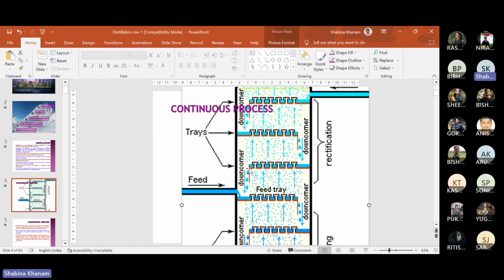Okay, so between here to here, we can say holes are available. That is from inlet downcomer to outlet weir, right? Inlet downcomer to outlet weir, and this area, whatever we are considering, we call the active area or bubbling area, where bubbles can be formed, where the vapor will be available. Vapor will not be available in the downcomer section. However, vapor will pass through these holes, and it will contact the liquid and form bubbles.